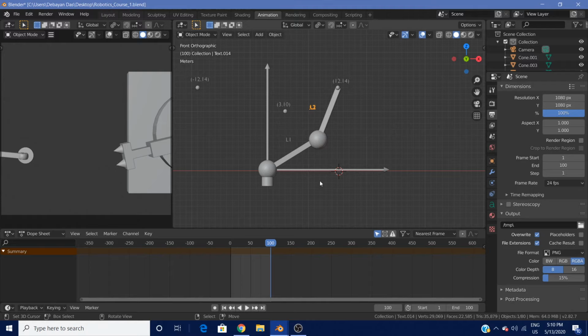value would simply be L1 sin theta 1 plus L2 sin theta 2. And with that, we could calculate the relation between theta and x, and we could differentiate that to find out what the velocities, etc., would be. And in fact, that is one of the most used examples that you'll see on the internet if you do